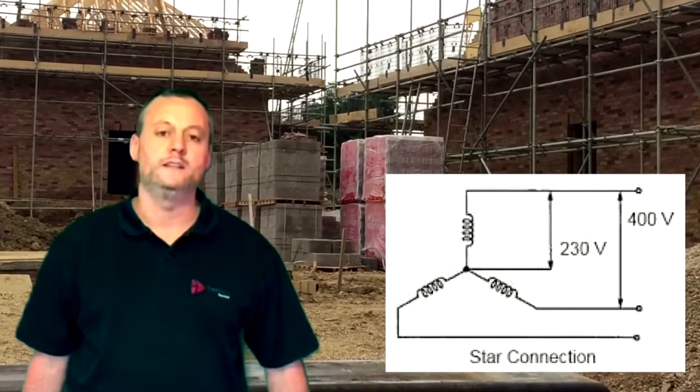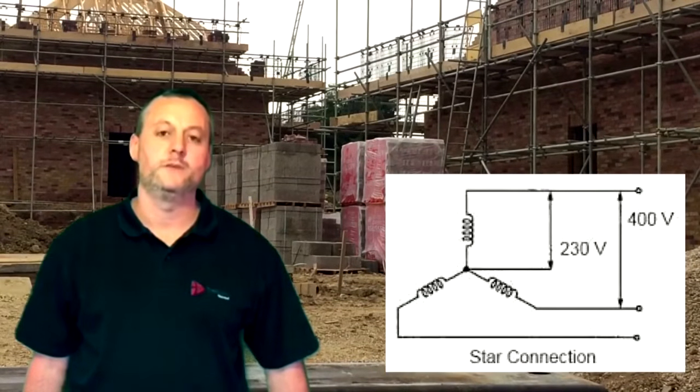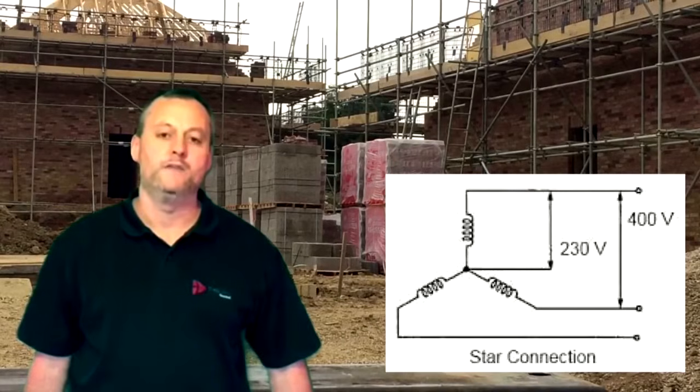We looked at a star connected load where a neutral was introduced. The reason the neutral was introduced is so we could have a single phase supply of any one line and neutral, giving us a single phase supply, where delta didn't, because delta only had 3 lines and you couldn't generate a single phase supply from it. We then went on to look at the section on star and delta connected loads and the mathematical relationships between line and phase currents and voltages. Again, a trickier section that requires calculations, but some bits can be remembered without the use of a calculator.